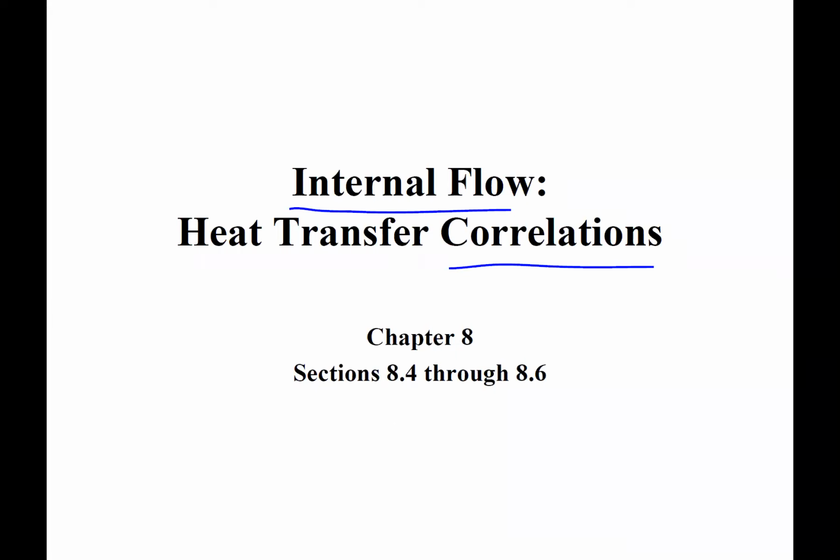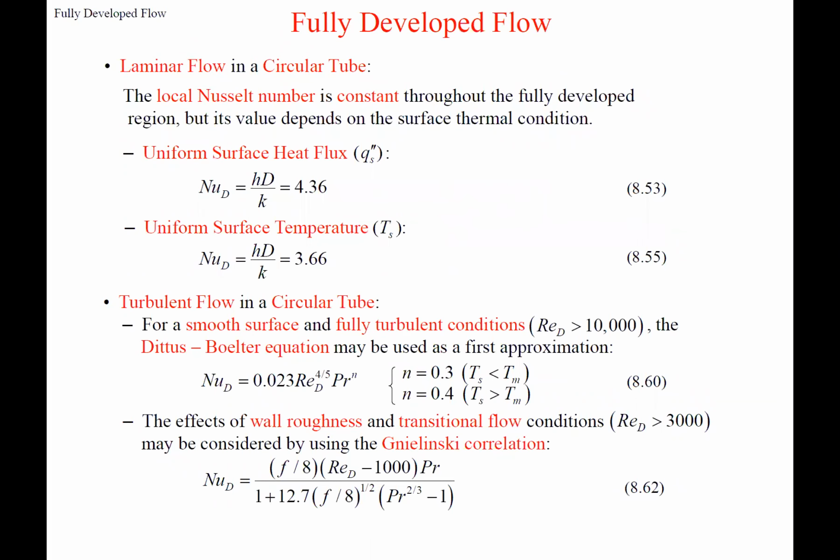We haven't talked about, for internal flow, how you get that Nusselt number and convection coefficient. So we have these different considerations. If we're fully developed, we determine that our length is greater than the entrance length thermally and the entrance length hydrodynamically, so we're fully developed flow.